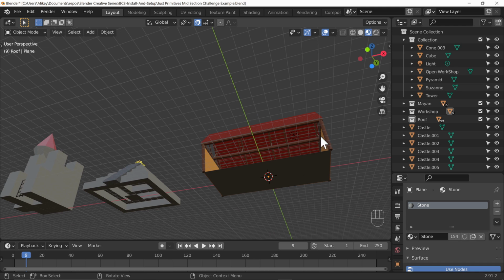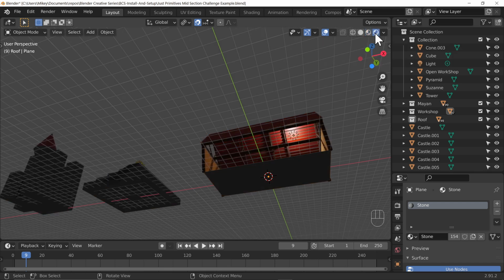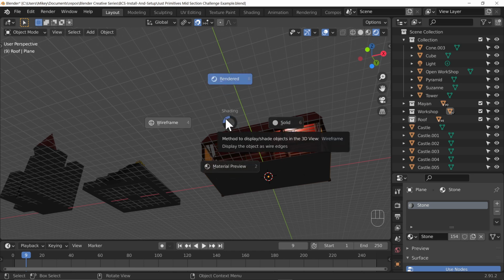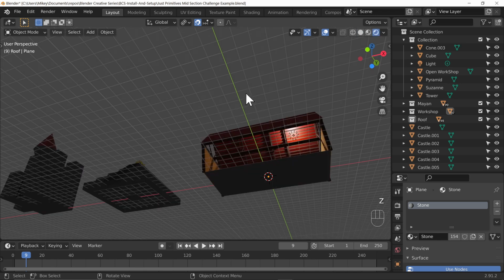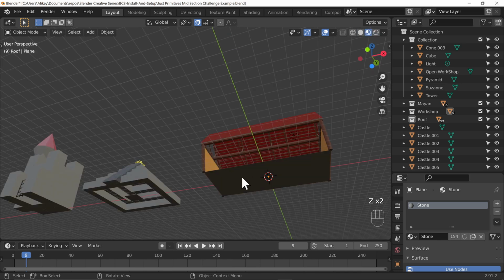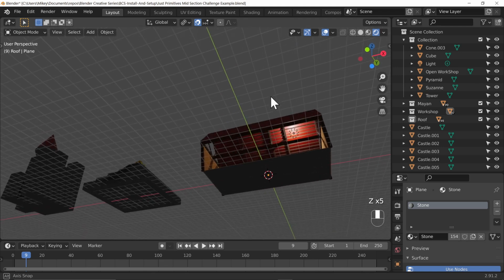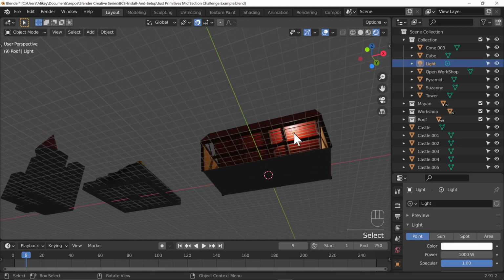Now, in order to see the lighting, we're going to have to go to rendered mode. So the final and fourth option on the toolbar at the top of the 3D window here, or of course we could press the Z key and it brings up this radial menu. And if you're really quick, you can just go Z and lift the mouse up and it will automatically switch. There we go. So much like mesh objects, we can just duplicate the lamp that's already in here.